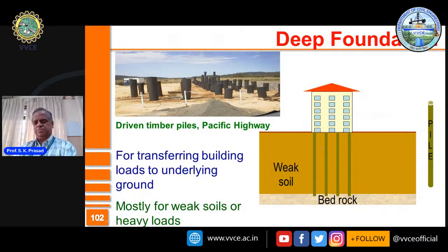When do you go for deep foundation? Two important reasons. When the structure is very complex. Two, when the soil near the surface is poor, so you take the foundation deep up to stronger soil like bedrock. Naturally, it may be more expensive. It may require sophisticated equipment, good expertise, a lot of time, and so on. But you can use pile foundation, which is a deep foundation, to solve problems like this whenever you have a weak soil near the surface.